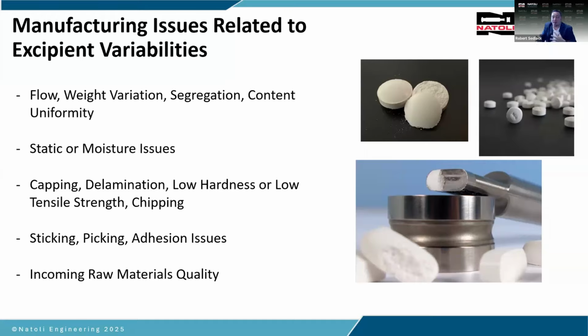We talk about sticking and picking adhesion issues. So sticking is probably the number one tablet defect in the world, where your material is sticking to that punch face. So on the bottom right, you'll see that tool with powder stuck to the cup face. That is a common issue. That could be from excessive moisture. It could be from particle size distribution issues, and it could be just a sticky material, but not always.